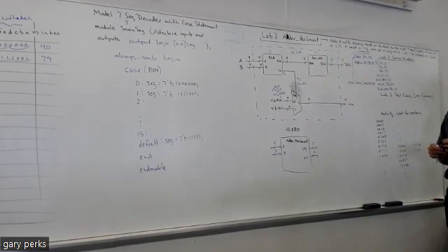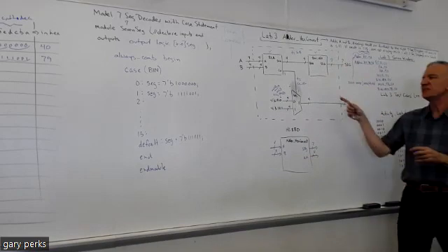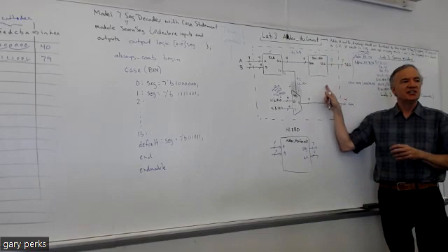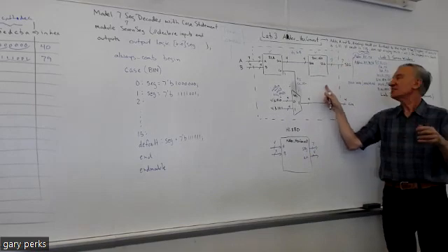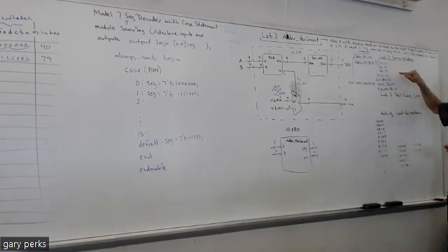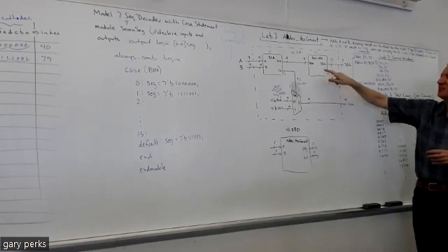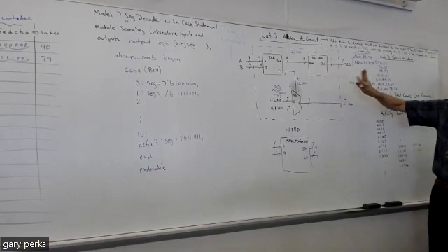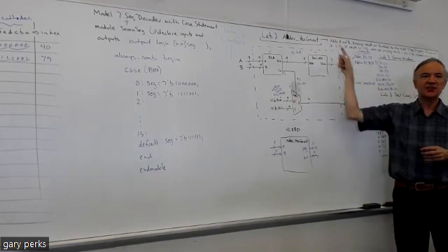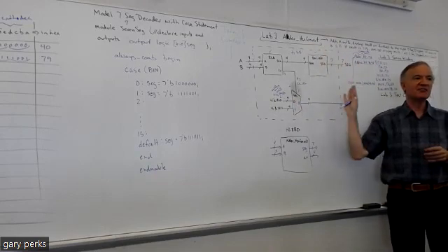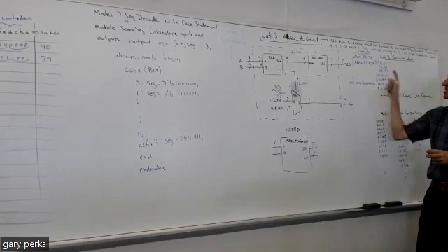Let's see, do you have any other questions? Are you all confident that you at least know the process? Because again, if you haven't done the mux, that's where you want to start. Bringing this over from lab 2 should take you all of 5 seconds. And after you're done with the mux and you have it simulated correctly, you want to do the decoder. Once you have that simulated correctly, then you do the overall structural model, connecting everything up. And then you have to test that.